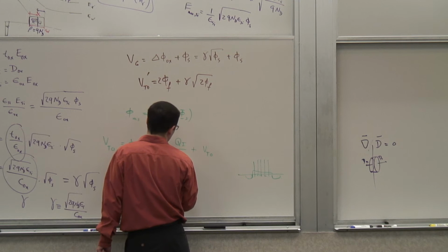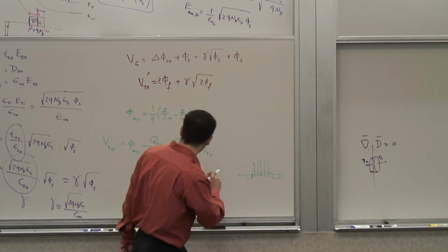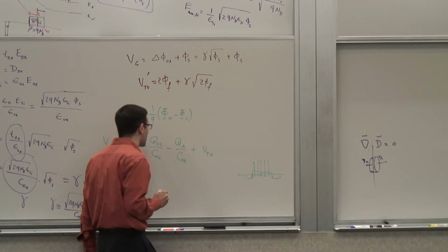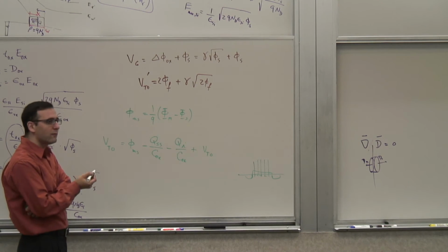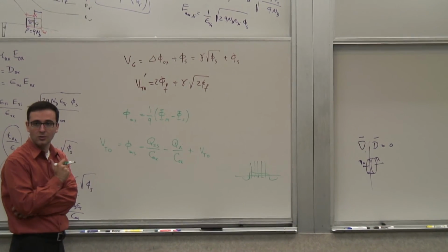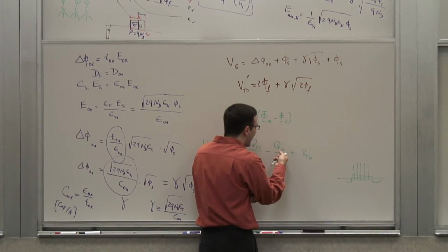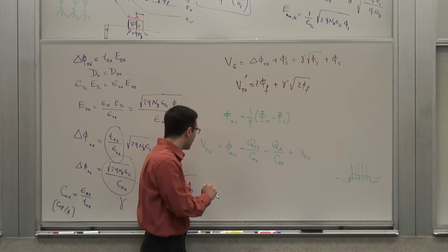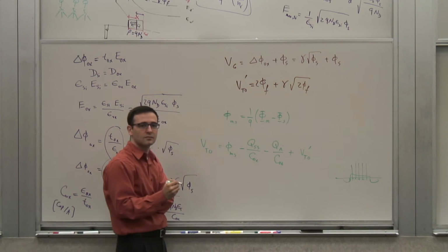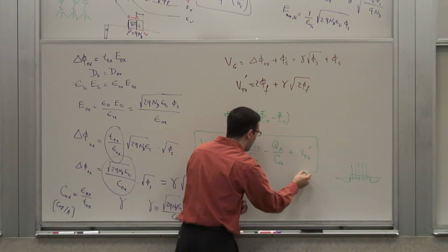And that Q implant is also, did I use lowercase i? Yeah, keep it consistent, let's keep it lowercase i. So that's the final term, and it is what I control, probably the only thing I control in this equation. I just implant enough charges there to get this voltage to what I want it to be. So now, in the end, this is my threshold voltage.